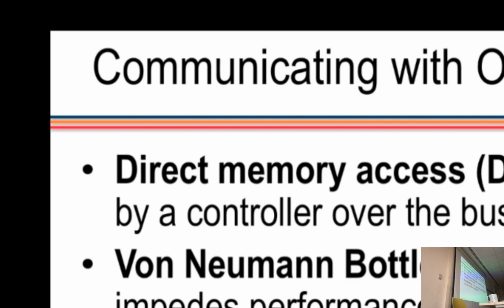Sometimes you send it, but he is not ready. So it is actually gone to the empty space. It doesn't go anywhere. But for reliable communication, you have to make sure that the message is actually received. For example, when you are writing from CPU to hard drive, the message is data. You shouldn't lose any of it. So you have to be sure. Therefore, a verification mechanism is required. That's what we call handshaking.